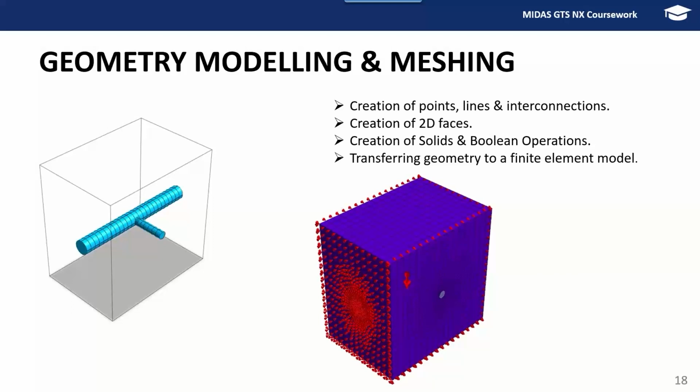Now we'll start with the geometric modeling. So this is how the geometry will look. Again, the soil body is made transparent, so that the inner solids are visible. These solids have been divided into 25 segments on the main tunnel, and on the cross passage, just near the intersection, the cross passage is progressing at an advancement rate of 0.5 meter, and after a distance of around 2 to 3 meters from the main intersection is reached, the cross passage starts going up at a segmental length of 1 to 2 meters each.